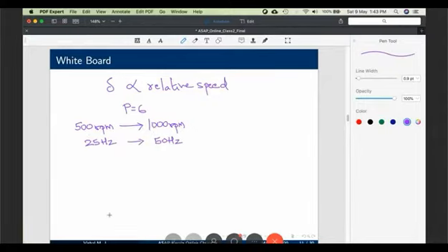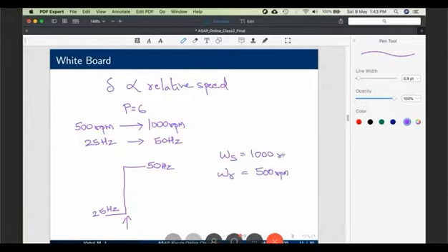The issue there is that if you give a step change in frequency, this is 50 Hertz and this is 25 Hertz. If you give a step change here, 25 immediately jumps to 50, then we have some issues. What is it? Now, what is your new synchronous speed? 1000 RPM. Because the moment you apply 50 Hertz, the speed will immediately change. It is an electrical domain. Whereas rotor speed is still at 500 RPM, the earlier speed.